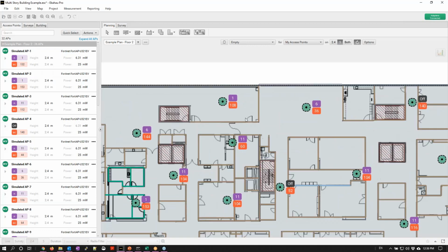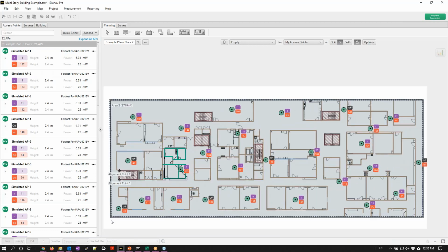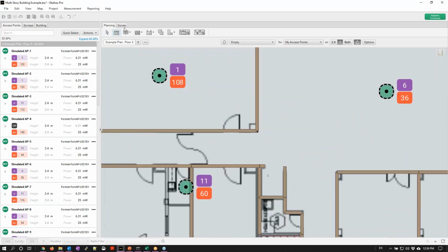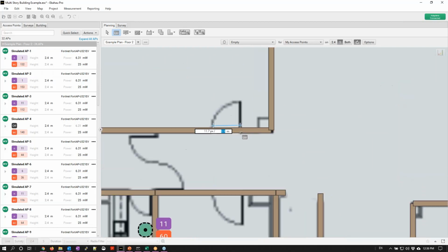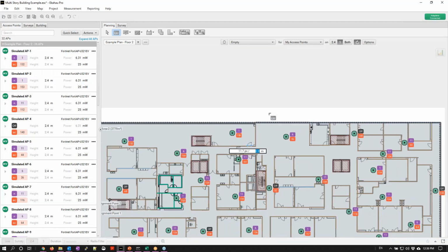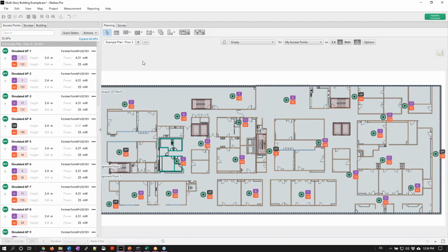So generally, a lot of the time, if I've used Google Map images, if I don't have a full scale on it, if it's an architectural design PDF or something like that, if it doesn't have a scale that I can use, and I use outdoor measurements on Google Maps, you could then come in and use your measurement tool here and go, okay, let's just double check how accurate that was. And that itself, that's 900 mil. So the scaling on this site was actually pretty good. So again, just a bit of a real world example, and great question, so thank you very much.